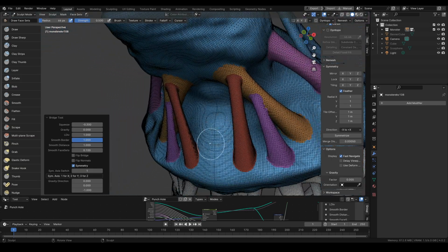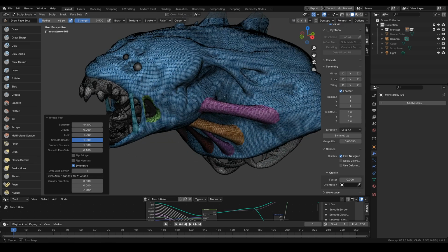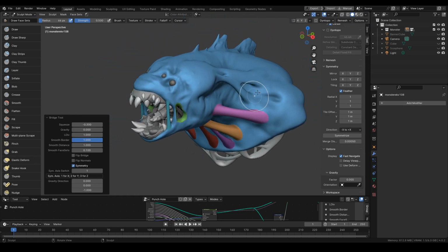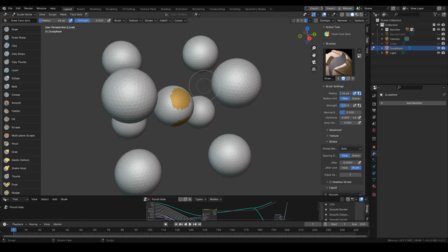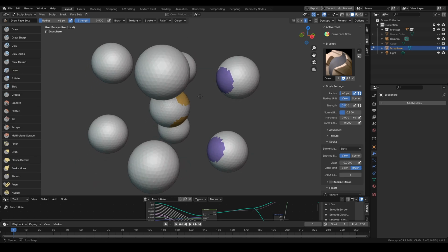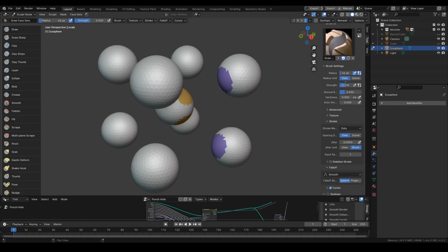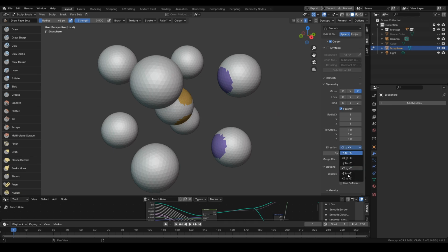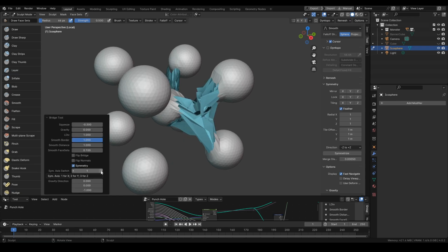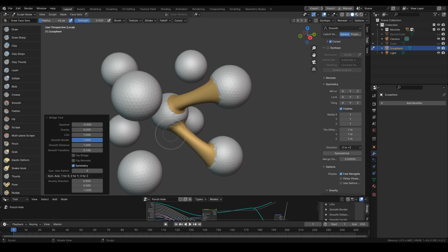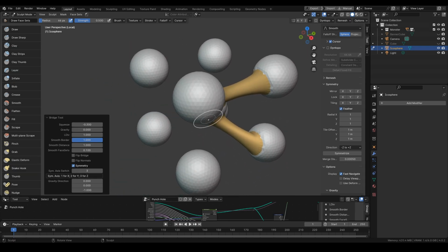So that's it when we are using the x-axis. And at the end of this video, let's take a last look. What if we were to use the other axis for the symmetry? So let's use the z-axis. And like before, let's use the symmetrize operator for the mesh to be perfectly symmetrical. And now, don't be scared by this. We just need to select the correct axis. There in the description you can see that the number 3 is for the z-axis.